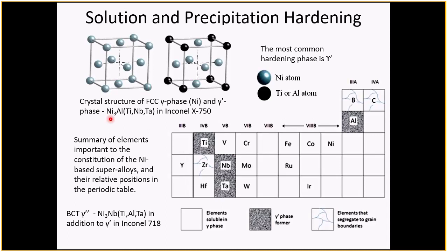So Inconel X750, that's used typically in engineering applications, some people might call it a superalloy because it's a nickel alloy that is good at high temperatures, but it really isn't classically a superalloy, because a superalloy, and if you remember, I talked about the physical metallurgy. I talked about this in one of the earlier lectures, either lecture 1 or 2.